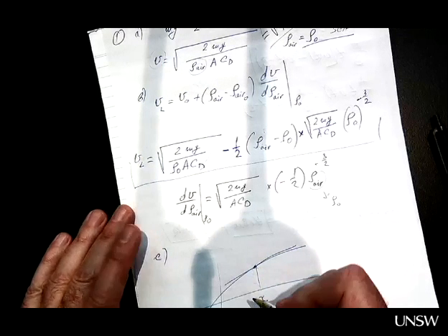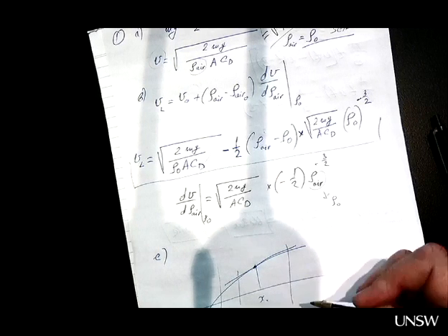So when you are choosing an operating point, you should choose it somewhere where the system operates. If you know the operating range, that the system normally works between x1 and x2, then the operating point should be somewhere in between those two, ideally in the middle.